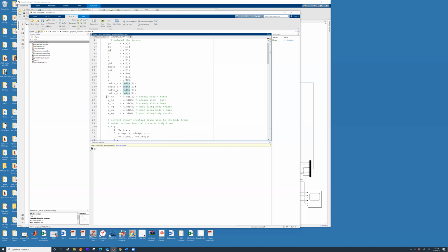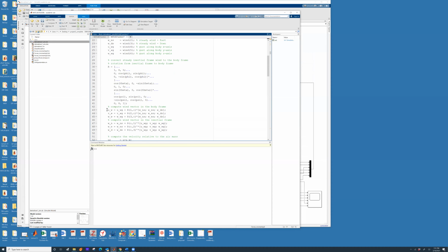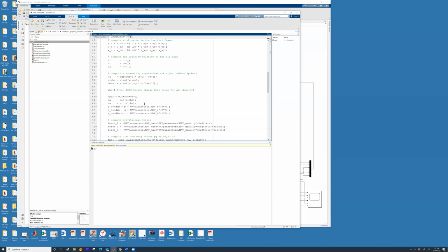So now there is this wind speed. There is no other change in the code except I want you to notice that the UAV parameters, mav.b, c, those now should correspond to Zagi. So you will have to change these. And this rho is the density of the air. So this rho will be something like 1.2 or 1.3. Please make this change. For kicks, if you try rho equal to 1000, you will notice that your simulation will be unstable because that is not the correct density.